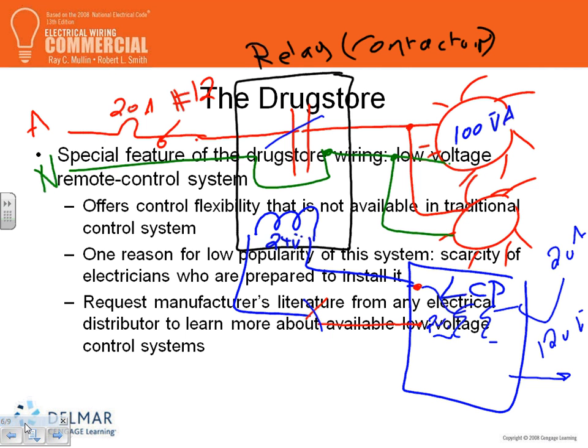The problem is that the fixtures in that particular area are old ballast with T12 eight-footers, so when you walk in the room and turn on the toggle switch, the control panel just goes chum. Yeah, it's like the contactor. And all of a sudden there's buzzing everywhere.